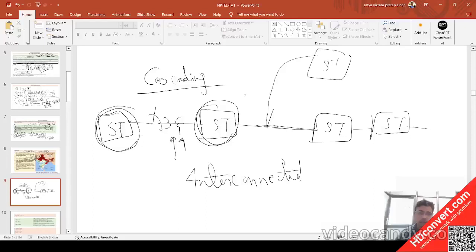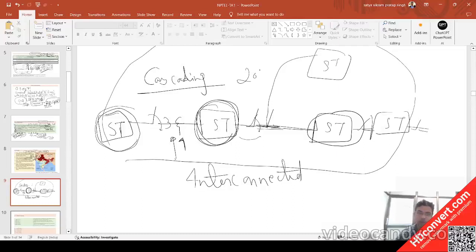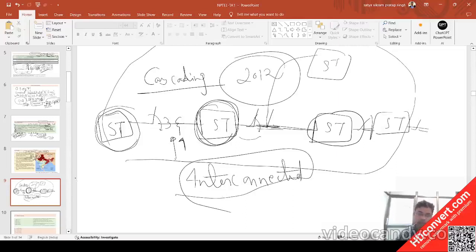At that point of time, the loading was still there, so this substation has to supply that loading. This substation also got to a very high level, so this also got tripped. So that loading has to be supplied by another substation, which then needs to bear this power. That created a cascading effect of disconnection between the various substations. That caused the major blackout in 2012, because our grid is very interconnected. Okay, is it clear?